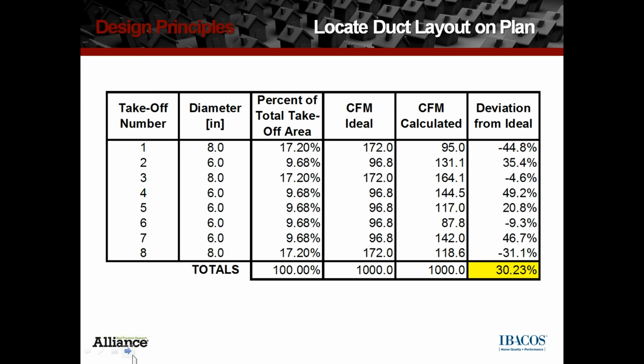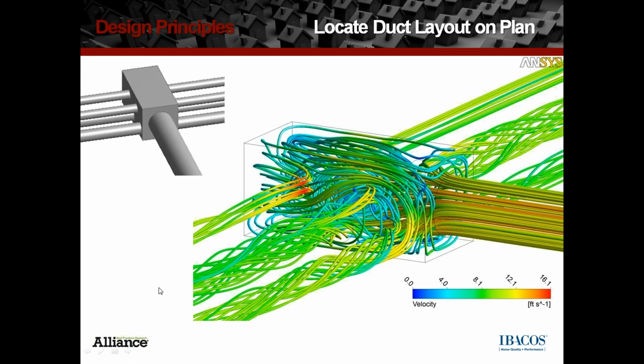Another way to approach the splitter boxes, and one that we often talk about in the field when we're walking, is bringing the supply into the side, not the top, not bringing any outlets directly in line with the inlet supply, and then creating, if you can see my mouse moving up here in the upper left-hand picture there, an extension to the end of the splitter box that will create a pillow of air to allow the air to redirect where you want it to go.